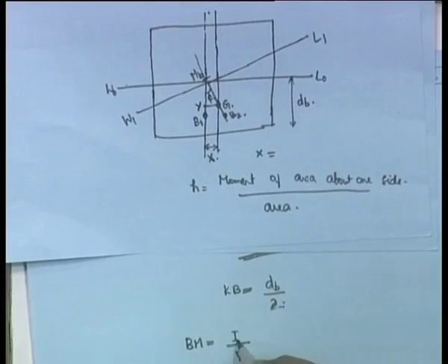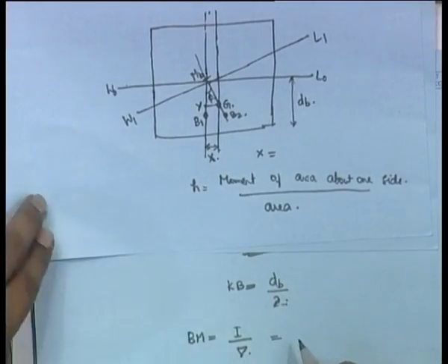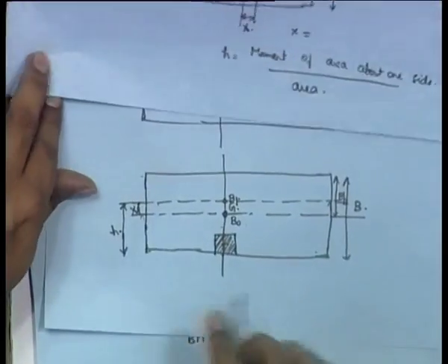Now, this problem becomes slightly more complicated, in that the volume on one side is not equal to the volume on the other side. Therefore, when you define the real center line, it is the centroid through B, the line that will pass vertically through B. So, it is not the exact center, because on one side some volume is lost, it goes slightly towards the other side. That is the point through which you have to take I. So, in this problem it becomes I about which point?